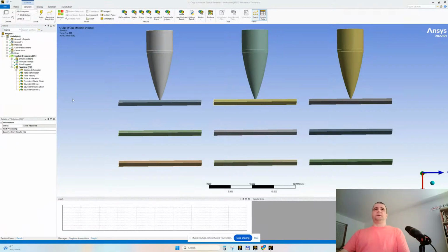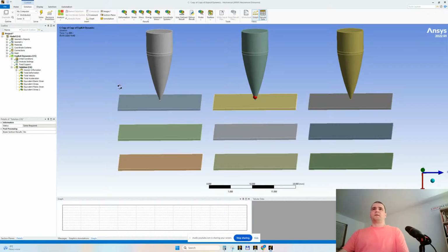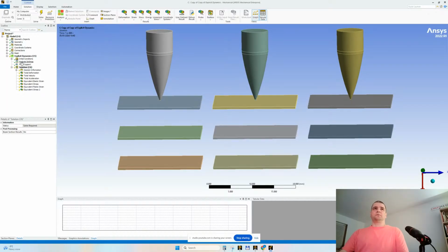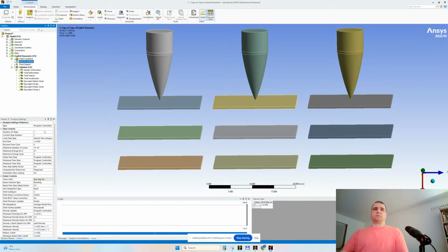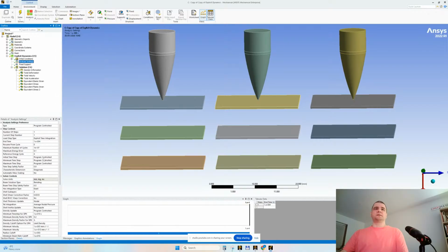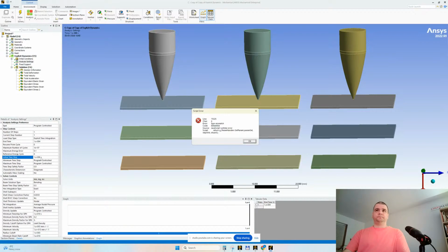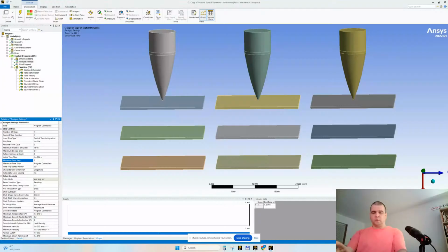Where were we? Here. The thing that I wanted to do since a while ago, because there are problems with the time step, let me assign time steps. 1e minus 6, this is my preference from experience. 1e minus 9 and 1e minus 6. Feel free to read, minimum, initial, whatever.